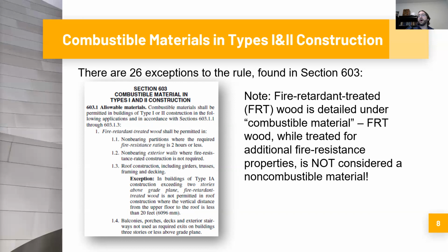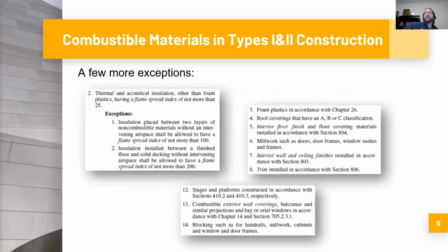You can't use non-FRT wood though, meaning you can't use standard untreated wood in this capacity. You can only use FRT wood. And again, this is an exception to the requirement for non-combustible materials. So a few more exceptions.